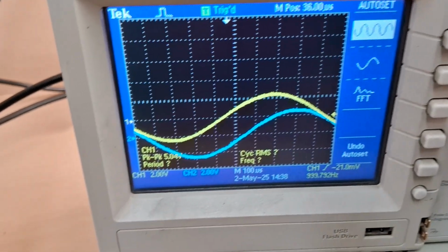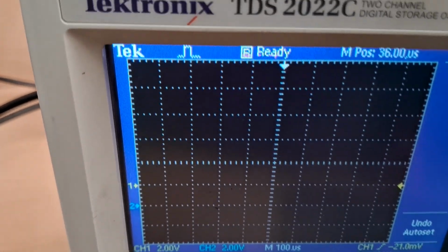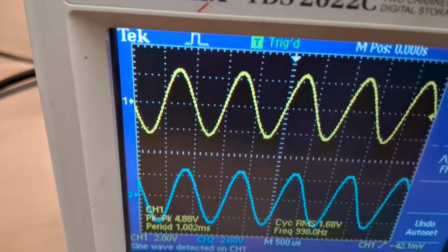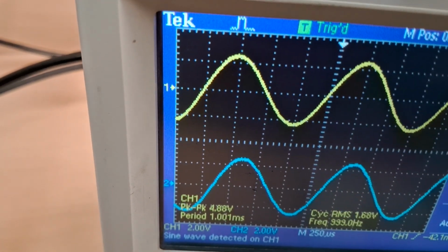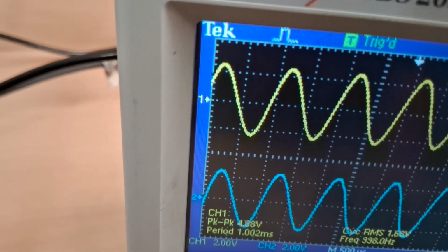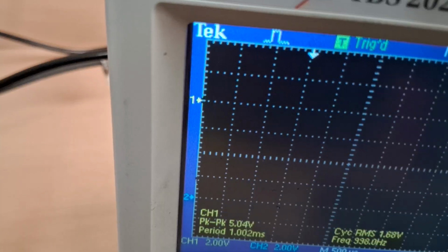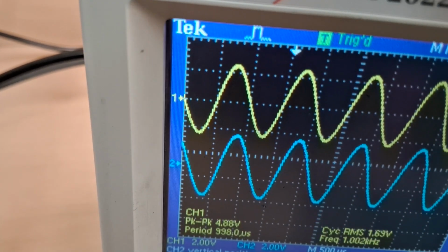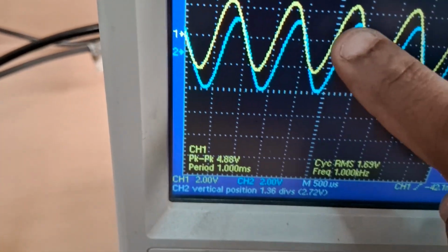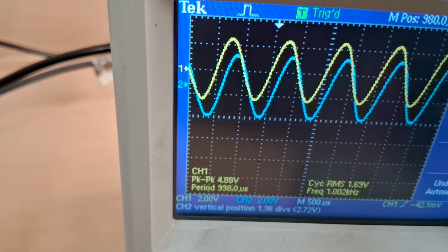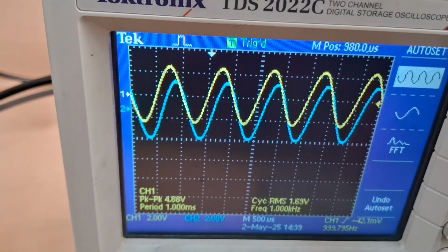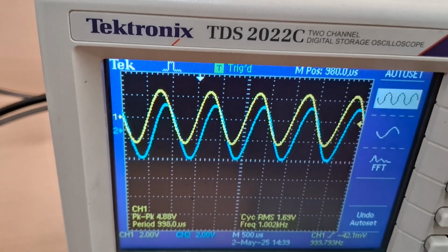See here, it's auto, you can see both the signals are the same, the transmitted and the reconstructed are both the same. You may see a delay between the two, and that delay is due to whom? The low pass filter. The low pass filter charging and discharging may create a delay, and that is the delay you can see between the two waveforms. Otherwise the frequency of the transmitted and the reconstructed is one and the same. So this is your sampling process which has been done.